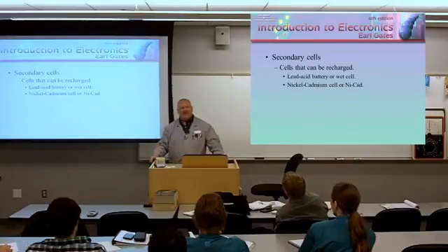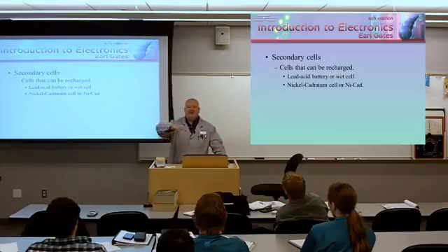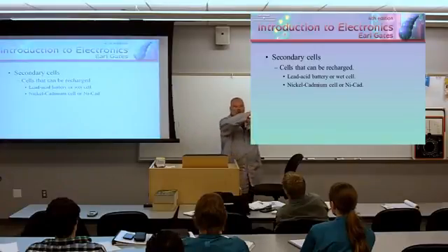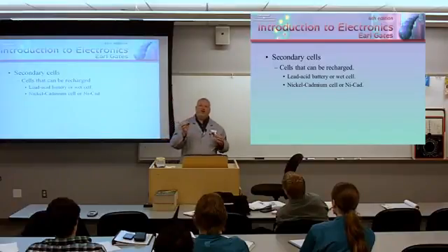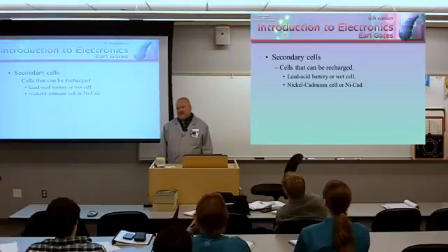So the problem with NiCads with things like camcorders and cell phones, as soon as that voltage started to drop a little bit, you start to get the low battery indicator. And to preserve the electronic integrity of what you were doing, it would shut off. Then you'd stick it in your charger, charge it back up, and what would happen? It would only get used to operating in this little realm right here. Some of the manufacturers got smart and they put a little button on there and they could connect it to a load and drag it down all the way and then recharge it all the way. Because I understand this stuff, I've gotten exceptional use out of NiCad batteries.